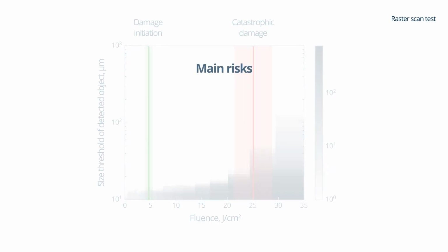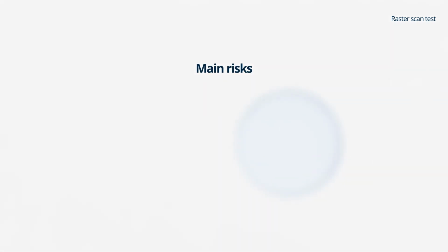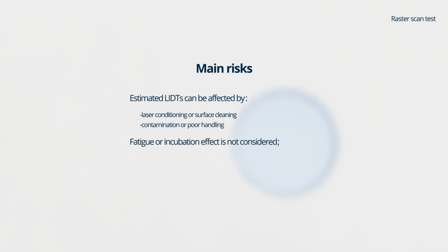There are also several risks associated with this procedure. As the laser irradiation level is ramped over the same area, laser conditioning, laser cleaning, or fatigue incubation effects are expected depending on chosen scan parameters. Accordingly, estimated LIDT values could differ from those estimated by other testing approaches.